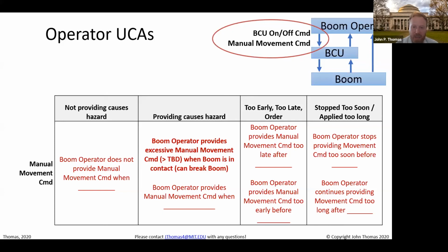If you were to propose that, I would say, let's ask the safety folks in the room, are you comfortable with that? Do you really want to tell these operators, go ahead and push the stick full up and down while it's coupled? Trust me, the BCU is going to ignore your movements. Or should we just consider the worst case and say, hopefully it doesn't listen to the stick movements, but don't go pushing it full up or down while it's coupled anyways. Of course, we would do the latter.